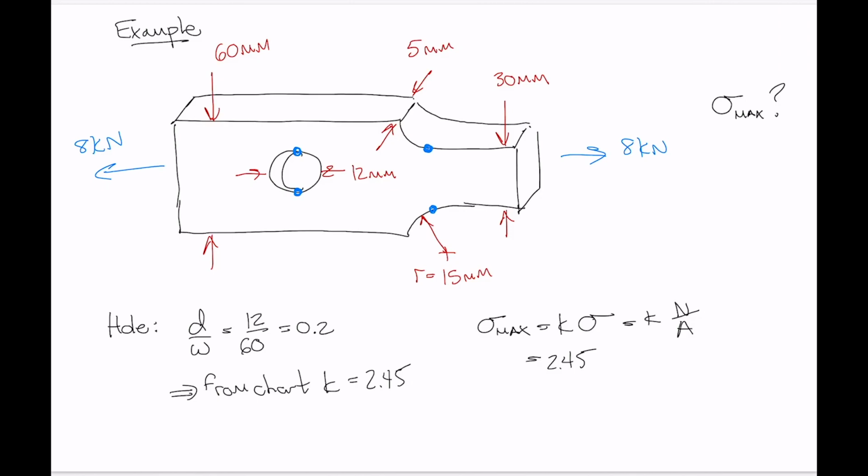Now, if we did a section cut through the location of the hole here, we get a free body diagram that looked, let's draw it in 2D, like this, where we've got 8 here and a total internal normal force of 4 on one side of the hole, 4 on the other side, so the total internal normal force is 8 there.